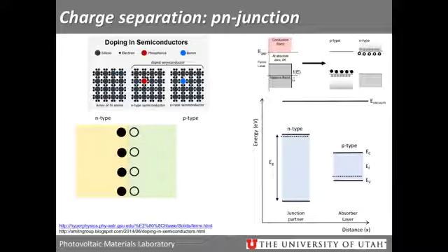When those are brought together, first, when a p-n junction is brought together, you have just a huge concentration gradient here. The N side has a huge concentration of electrons. The P-type has a huge concentration of holes, so you get simply some diffusion problem. Electrons want to flow from N-type into P-type, and holes want to flow from P-type into N-type. Does that make sense? What those leave behind is fixed point charges.